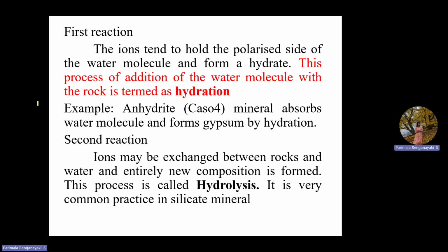Now let us see the first action, hydration. The ions in the rock tend to hold the polarized side of the water molecule and form a hydrate. This process of addition of water molecule to rock is termed hydration.